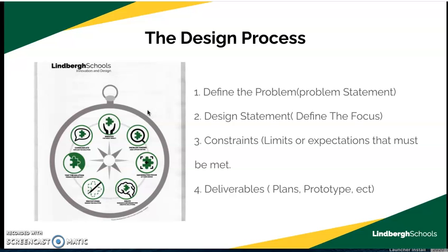In the design process, we have constraints. Constraints would be the limits of the size of the bridge. So our bridge is going to be in between 12 and 13 inches long. The road bed, or the distance across the bridge from one side to the other, is going to be a minimum of 2 3/8 inches. That allows us to get the washer in there and the bolt through to suspend the bucket. It needs to pretty much be 2 3/8 inches wide minimum to do what we need to do in order to test it.